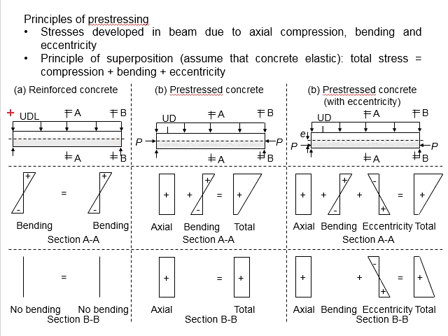The member is purely subjected to a UDL, which will lead to bending moment acting on the member. Based on the bending moment diagram, we know that the moment at the support will be equal to 0, while the moment at the midspan will be the largest. This is the reason that we look into two critical points of the member.